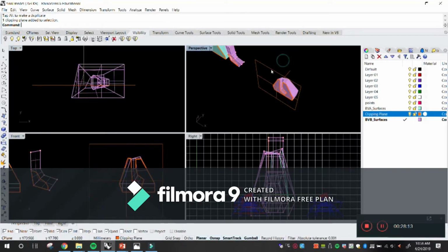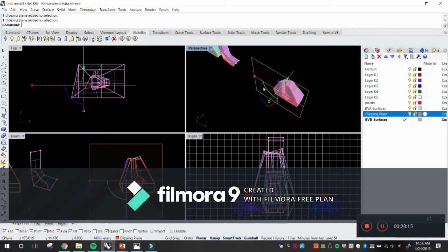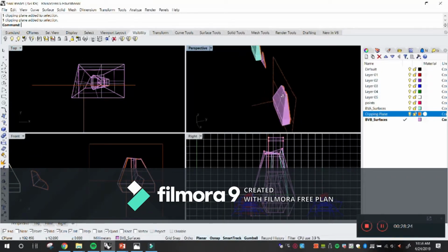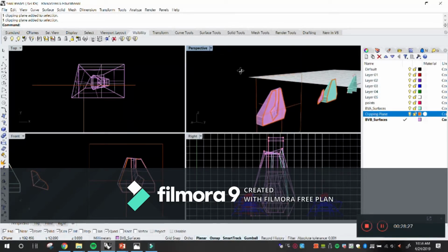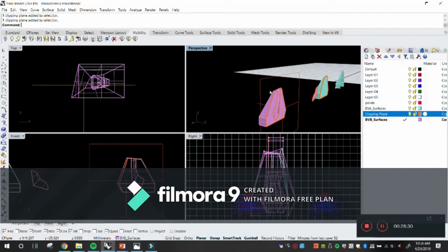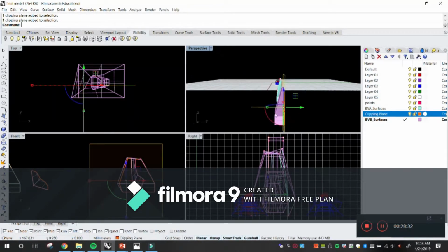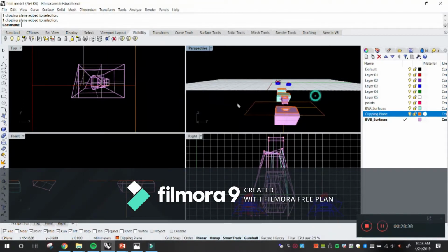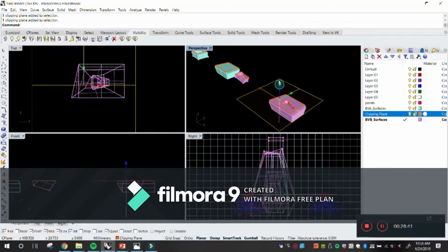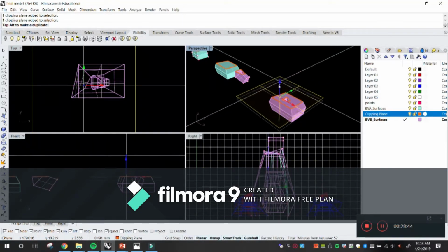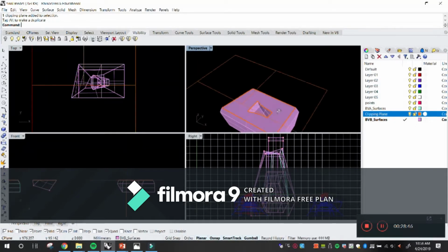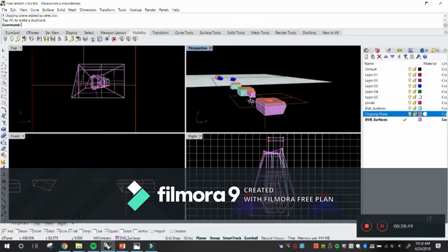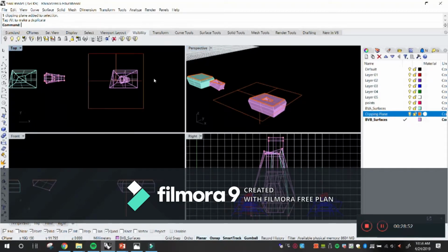Okay, so clipping plane is just like any other object. I can select it with the gumball. I can rotate it on this axis 180 degrees, and what happened? Now I'm looking at the other direction. Okay, let's say now that I wanted to do some sort of pseudo floor plan. What happens is now I rotate this 90 degrees, so I am now cutting through it on this axis as such. Okay, so I can start having all of these different studies on this form.